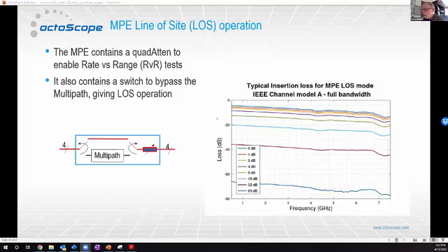So pretty much DC to well above 7.5 gigahertz, up into the 8 gigs. There is some droop across the frequency range, but it is a huge frequency range. If you were to zoom in, for instance, on the 2.4 gigahertz channel, you'll see it's pretty much flat across the 60 megahertz or so that the 2.4 gig ISM band offers.